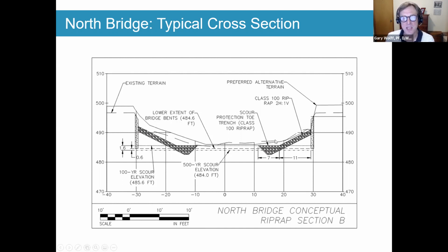And then the environmental regulations usually prevent, for stream and land permitting, any kind of hardened material inside what they call the scour prism. So basically it's some multiple of the channel width or just equal to the channel width, depending on the jurisdiction. And then they look at the computed scour, the general scour, the contraction scour I showed you.